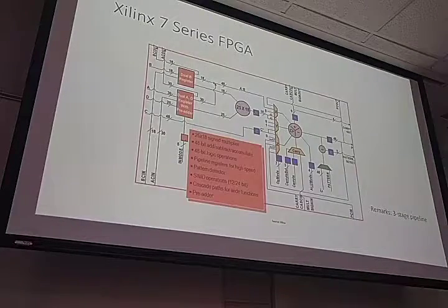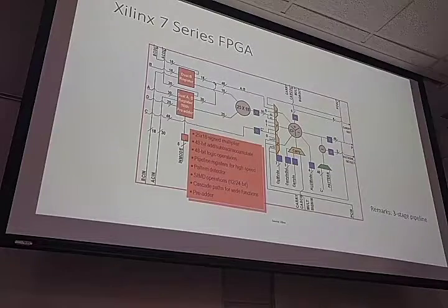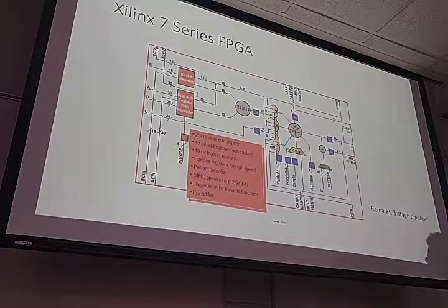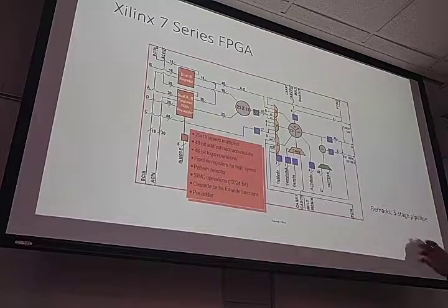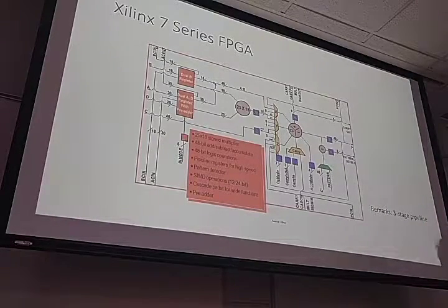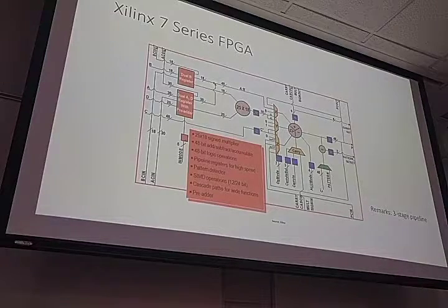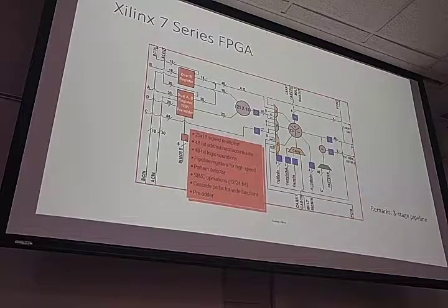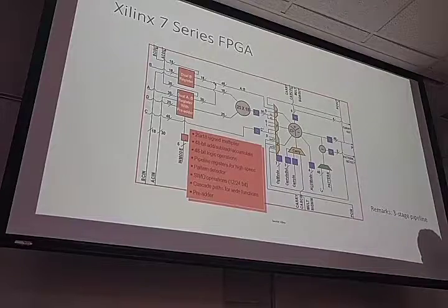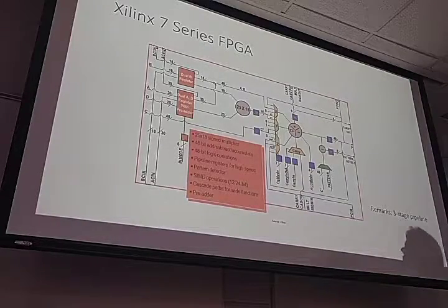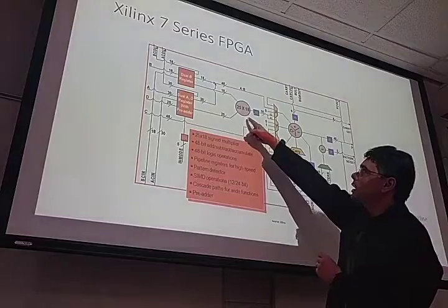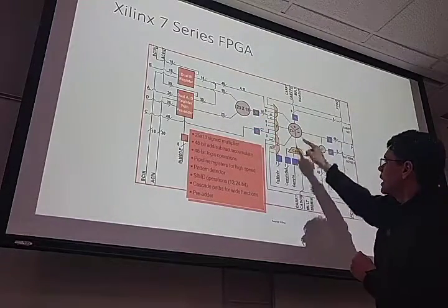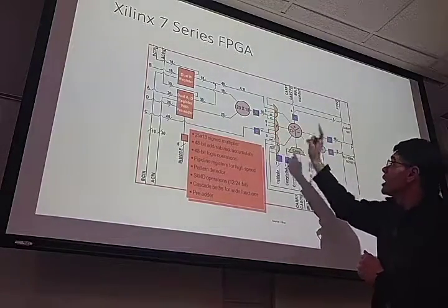Next one. In contrast with CLBs, you also have DSPs, which you can use instead of CLBs for a multiplication, for instance a scalar multiplication. DSPs are small blocks in the FPGA, very dedicated to mathematical computations, where you already have in silicon a multiplier and an accumulator.